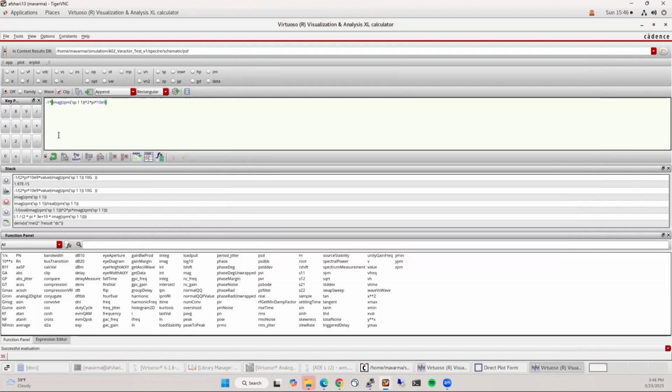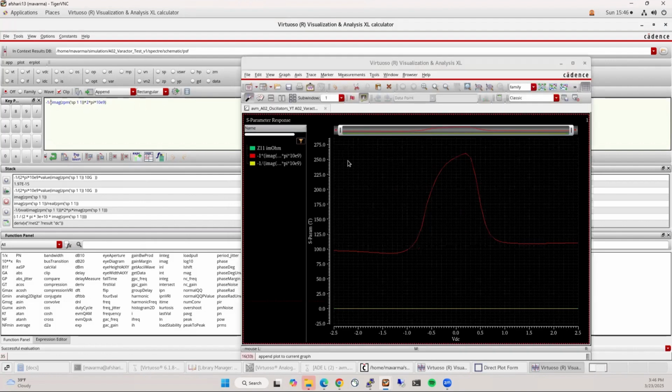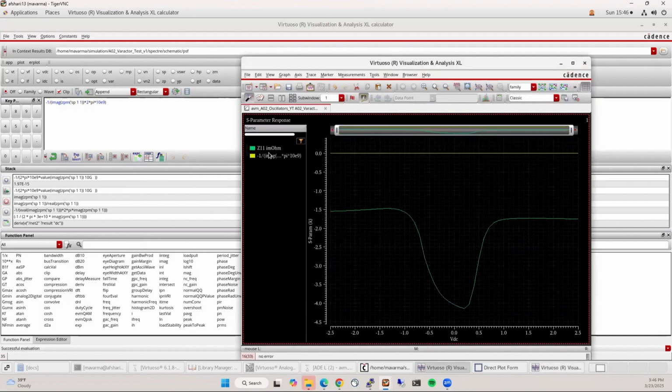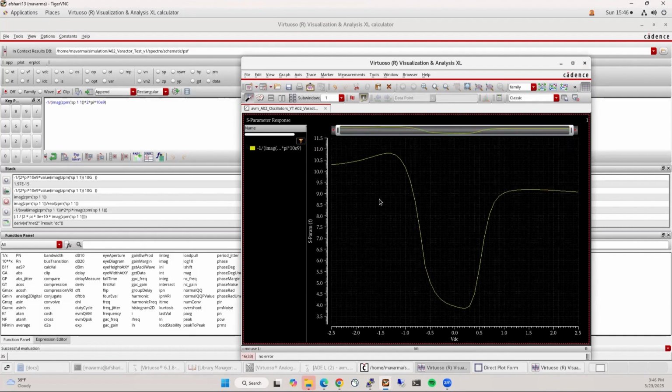Oh, it should be divided by. Okay. Delete that, delete that. Yeah, that looks right. Okay, so that's what we have. That's the capacitance. And you can see clearly that you have this kind of strong inversion on the right, and then maybe depletion, weak inversion somewhere in the middle. And then you also have the accumulation on the left, right?